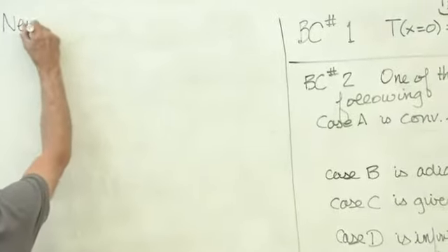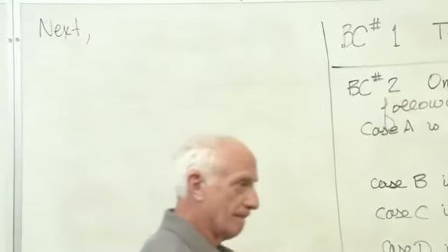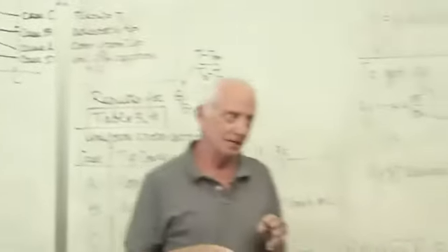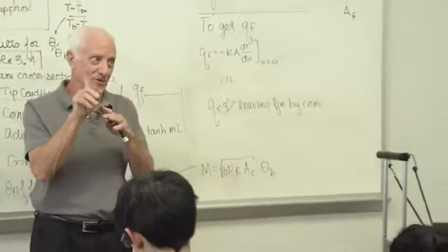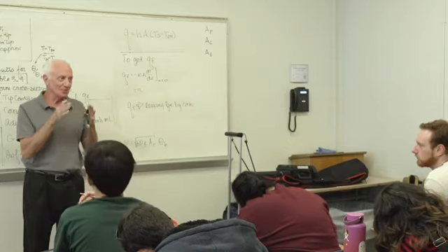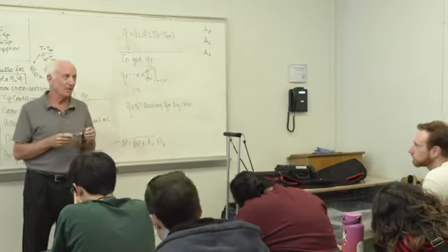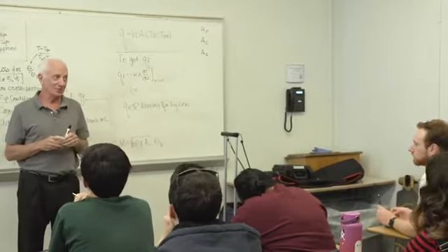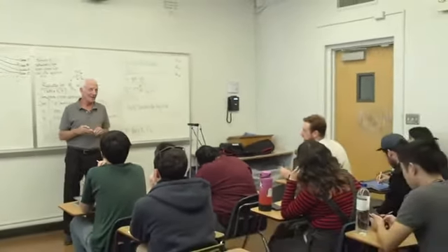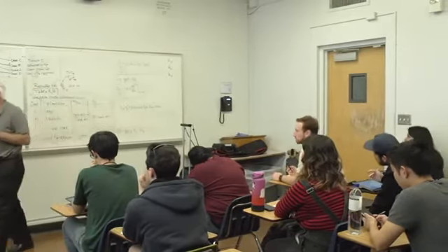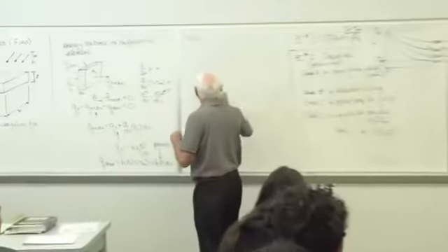Does this assume there's no change in temperature with the y direction? Right, good point. We're assuming one-dimensional heat flow. In reality, it's not. In order for heat to get out the top, there must be a temperature gradient. But the first model assumes that temperature only varies with x, not of y. We're going to do a numerical analysis problem in about 3 weeks in which it's a two-dimensional numerical problem, x and y. And you compare those results to these results to see how accurate they are. Good point. Next, we'll look at fin efficiency.